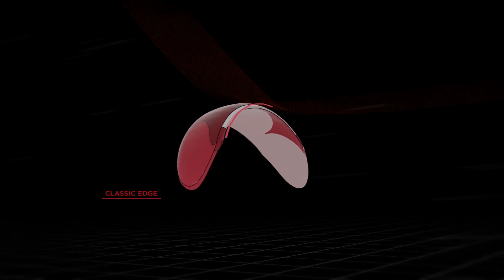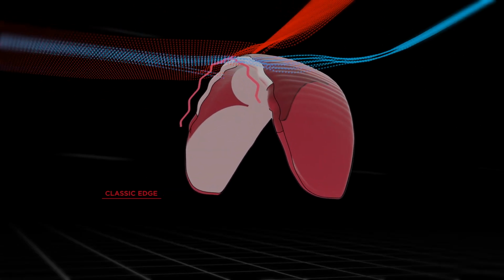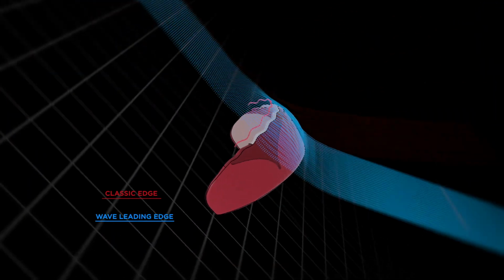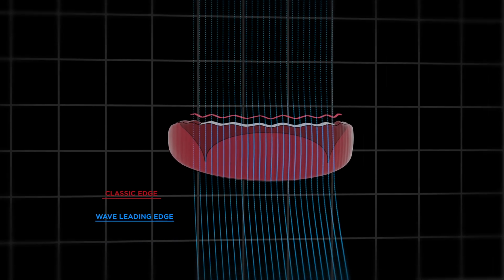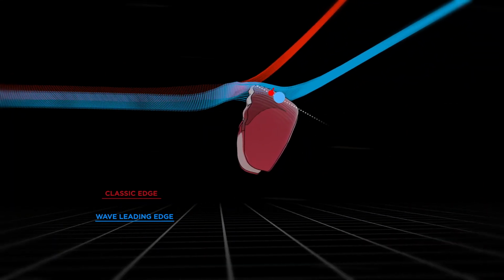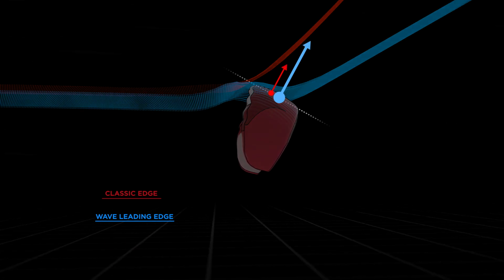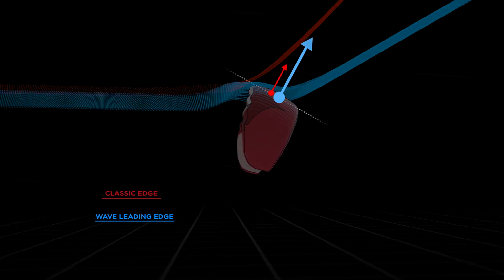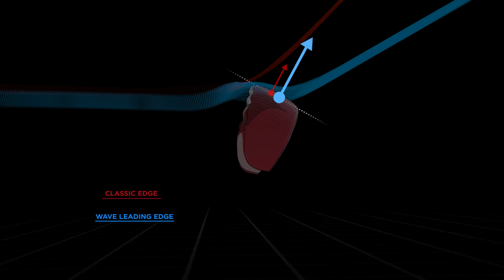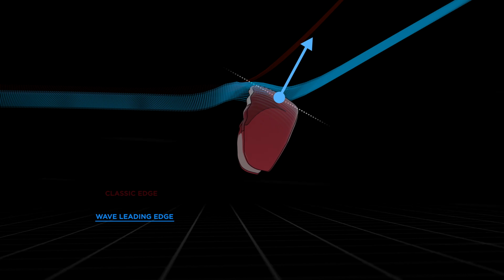Okay? And if you apply tubercles at the leading edge of the paraglider wing, then the pressure on the upper surface can remain small even at high angle of attack. So the pressure difference between the upper and lower surface can be maintained with large magnitude, and it will make the lift force generated by the paraglider wing remain large. Okay? So that's how tubercles at the leading edge of the paraglider wing work.